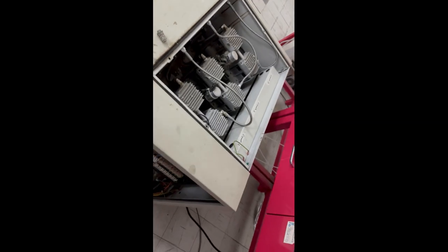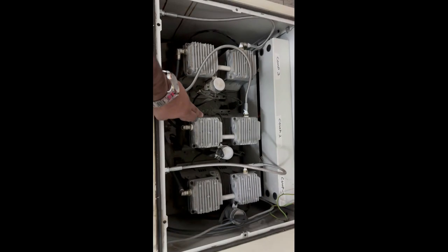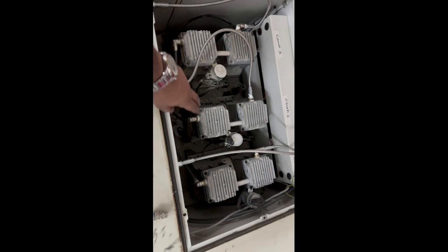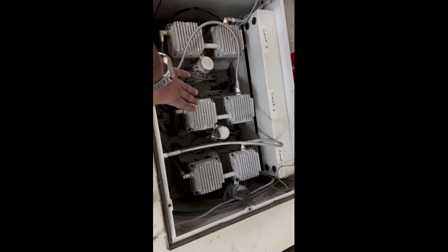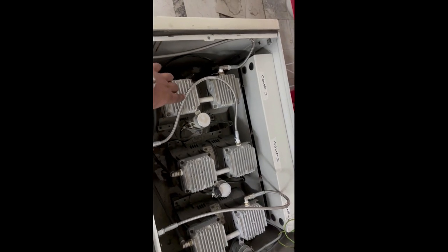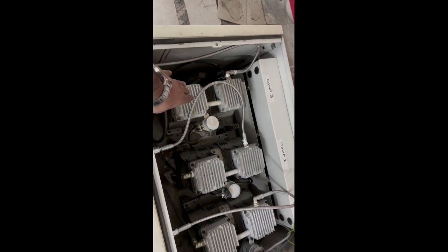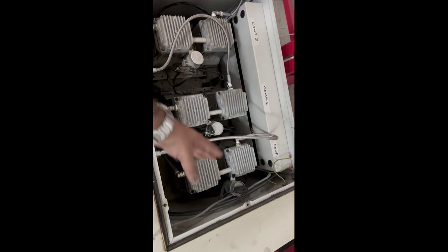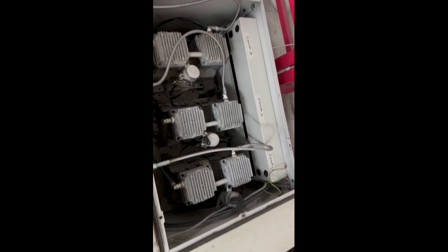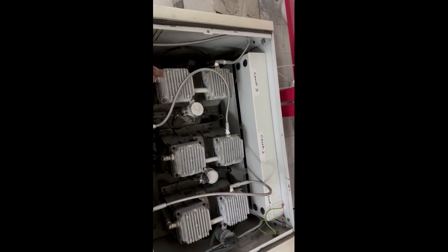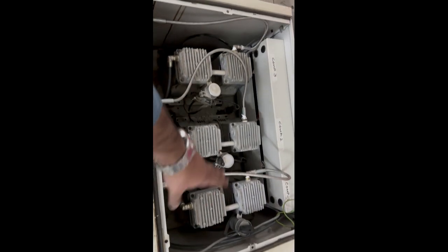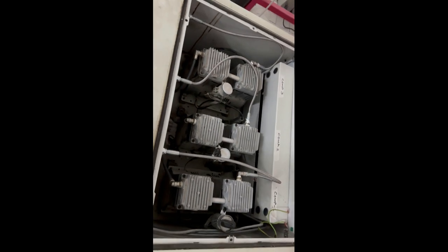Since we have 3 compressors, compressor 1 is for the nitrogen, compressor 2 is for nitrogen and air. So this is for both, because it has a valve located under here. It switches to send the pressure either to the membrane or to the tank. And the third one is for redundancy mode. It means if either system is not working or any compressor goes out of service, this will take over the operation and work in replacement of any faulty compressor.